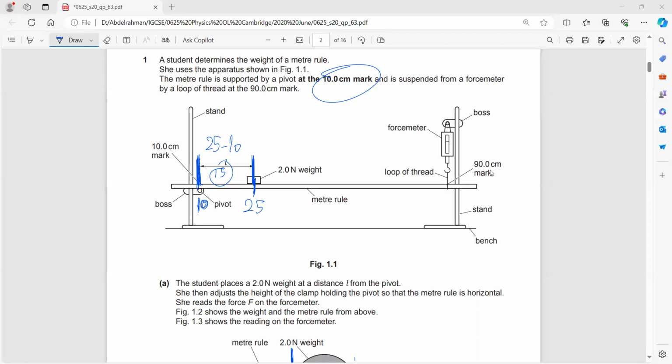As for the answer of the set square, what will I do? We'll put the set square like this and make sure that it is 90 degrees, and again put the set square on the other side and make sure it is also 90 degrees. This is if you want to use the set square. If you use the set square it's correct, you will take the mark 100%. And I personally prefer another answer, which is to just measure the distance between the ruler and the bench on both sides.